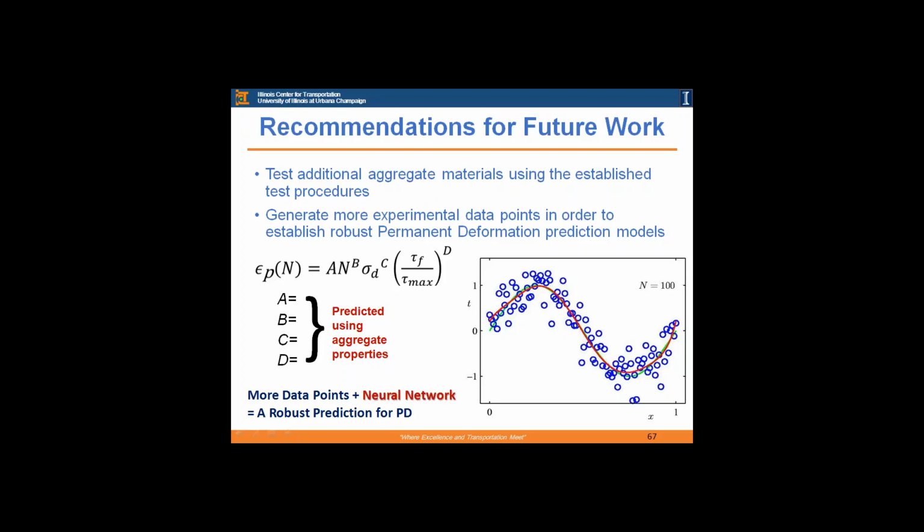So you cannot just govern by a stress ratio term, because the actual magnitude of the applied stress is not finally coming into the final permanent deformation calculation. So that's the reason both terms are needed. We went through this many times. I was looking at sigma D divided by strength, sigma D divided by tau max, but I'm sure you may have too. But that comes out as a stress ratio again, and the model takes that as a ratio. Sigma D is an applied stress. You divide that by the strength, tau max.